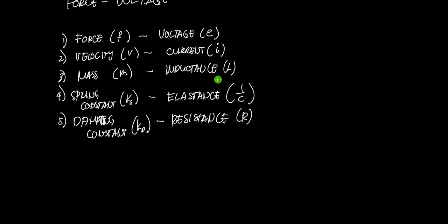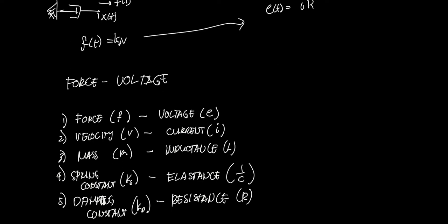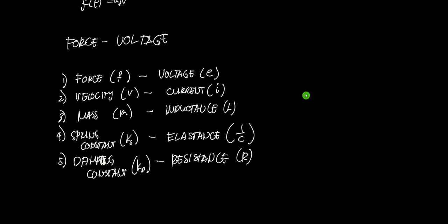In an electrical system, in a series circuit, the current through the components of a series circuit is all the same because they are in series. The same is true in a mechanical system because they are analogous. Therefore, if the components are in series, the velocities are the same. And also, the number of meshes or loops in a circuit depends on the number of masses in a mechanical system.